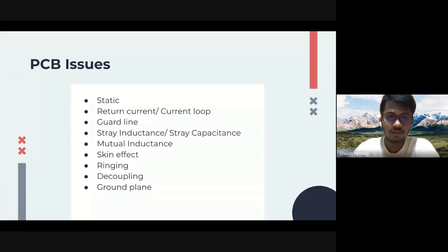And then when there is EMI, or when there is moisture, they create some static, and they can induce some noise into the PCB tracks, because this solder mask is really thin. So these statics, at high impedance circuits, like when you consider 100K impedance input circuits, even a small voltage like 0.1 or something can change probably an MSB or an LSB, which could be like 1% of the error itself. So at high precision circuits, static is also a problem.